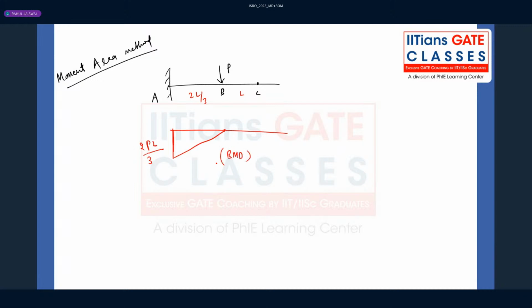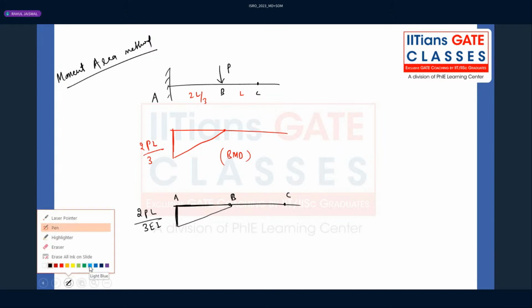But we are not interested in the bending moment diagram, because we are very much interested to know the M by EI diagram, that is, the bending moment diagram divided by EI. So ultimately, you will be getting the graph with somewhat smaller values than this. So here you will be getting 2PL divided by 3EI. Now, once we know this diagram, you can calculate the deflection at point C. How to calculate deflection at point C? You know that two theorems are there under the moment area method. The first statement is to calculate slope. The other statement is to calculate deflections.